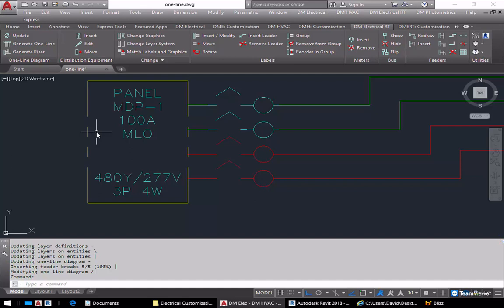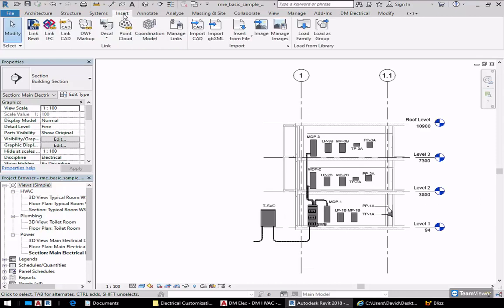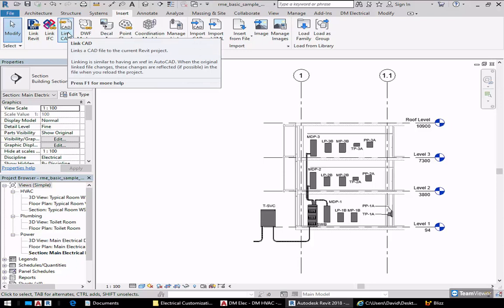And then another question, typically risers in Revit are not shown in color, but black and white and grayscale. How will transferring this drawing to Revit be depicted, in particular new versus existing? So when you pull things into Revit, you pull it in using the link CAD command, and that pulls the drawing in to Revit. And I honestly don't know what Revit does with colors versus line types. I haven't really investigated that with Revit.